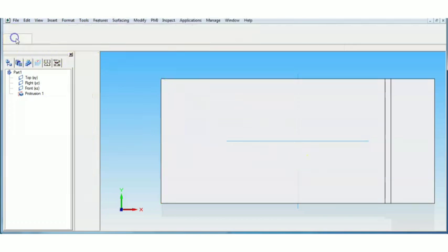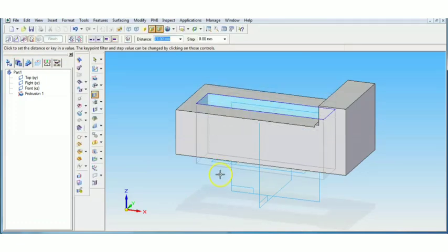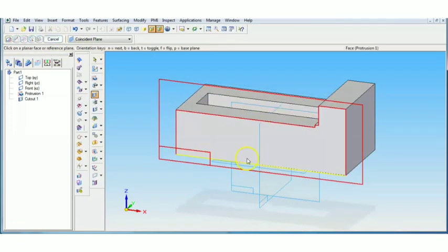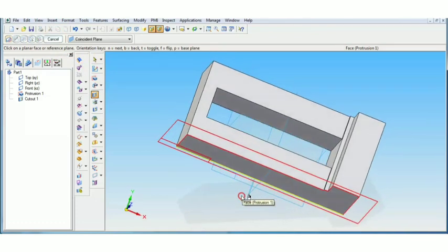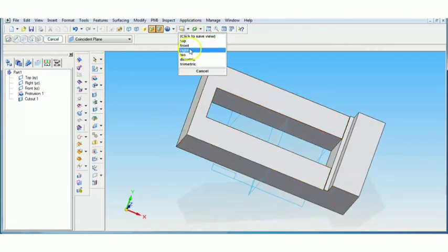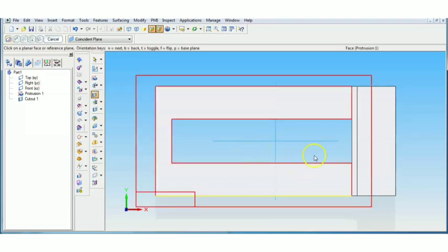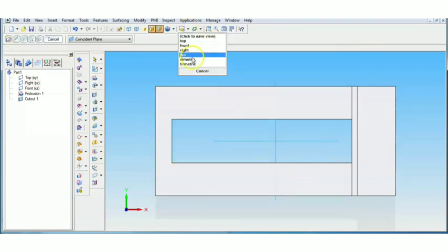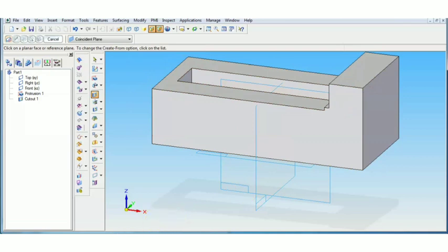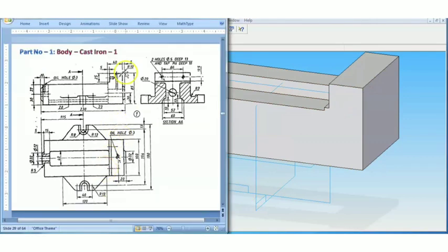Now just say return from here and move downside. Just place it, finish it, and you can see the cutout you have got. If you check it in the top view, you have got the cutout which is required. So again go to dimetric view and try to add the other features. I'll add this feature of round radius 10. Then I'll have this protrusion of diameter 30 and length of 5. This is also a diameter.